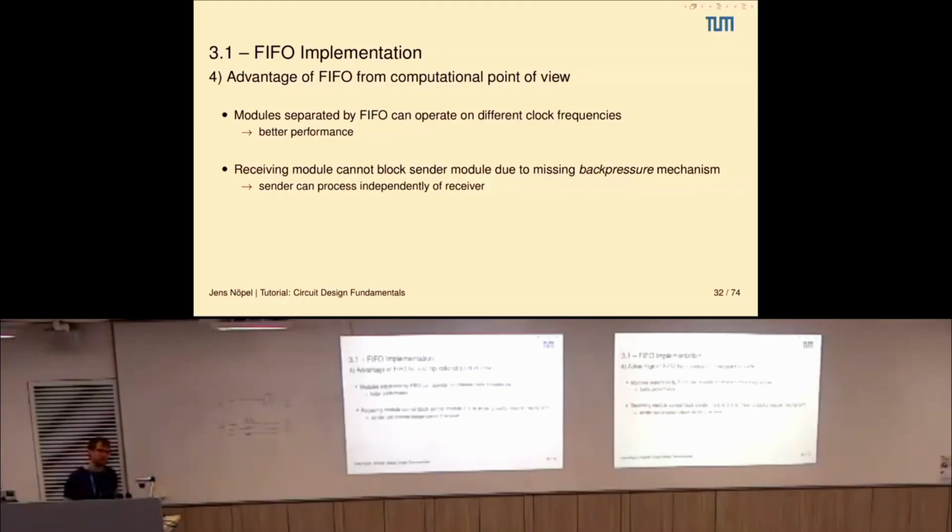Yes? So let's assume we don't have this back pressure mechanism here. We don't tell module A that module B is ready. Then what module A would do is just write data, say it's valid, and assume that module B is able to handle this data, right? And never do this back pressuring and say, I'm not ready. So this is then the assumption that module B is always able to receive data. And if that's not the case, then the data that is sent is just gone. It's just dropped.